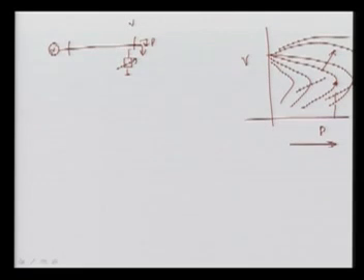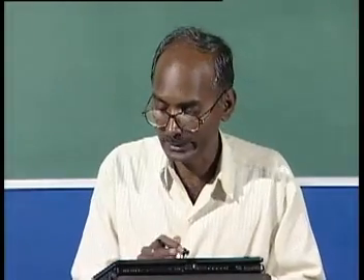So here it is lagging, and this side is UPF, I can say unity power factor, and then by providing reactive power support, we can go for more loading in the system, and then we can go for a higher voltage stability limit of the system. So with the help of a shunt compensator, we can improve the voltage stability limit as well, which I explained in shunt compensator. Now I am going to discuss the transient stability limit, and let us see how it is going to improve.